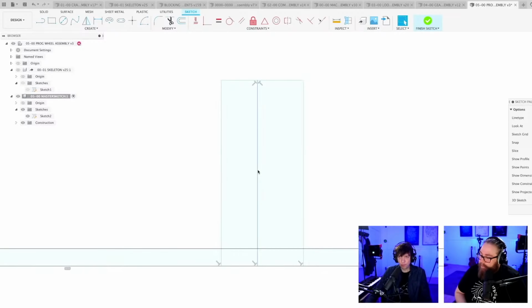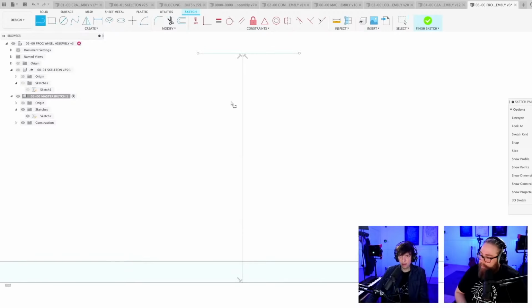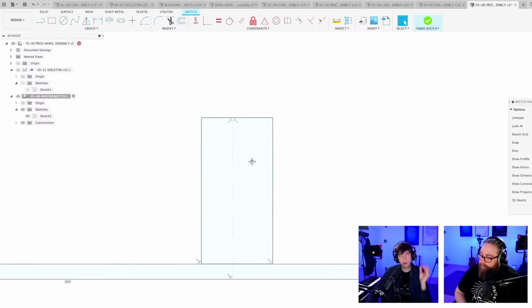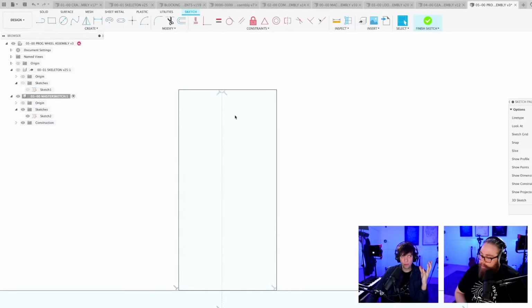But I want to use standard solutions, which means that on this machine, as much as possible, I want to use standard parts. And that, I think, is maybe the best argument for the belts, because you will have pulleys and belts in systems that are made for each other, and you could just order the ratios you want.